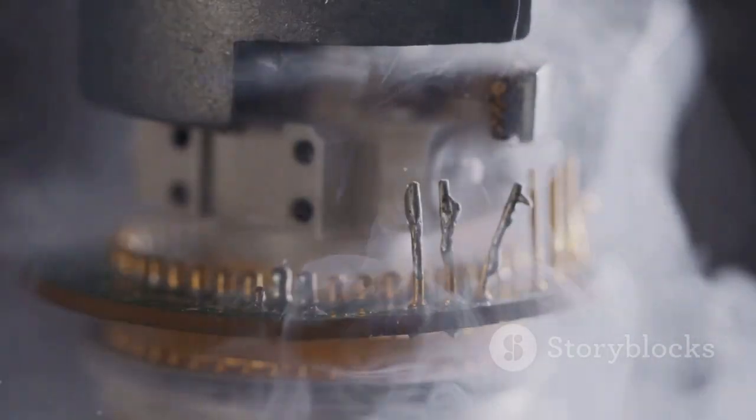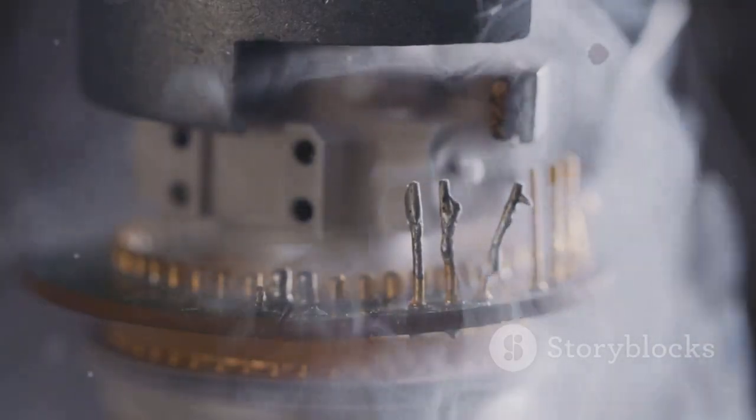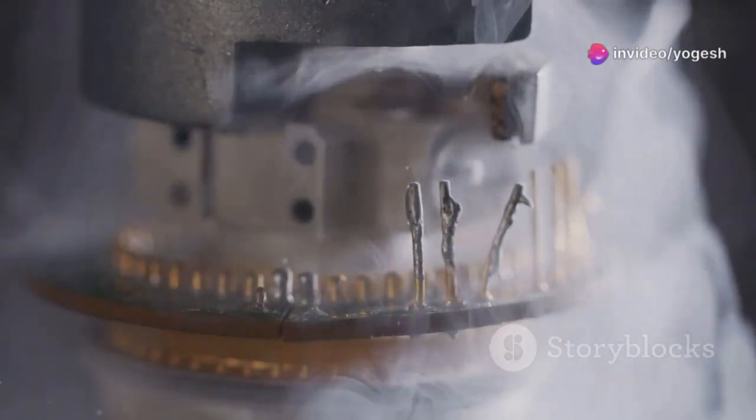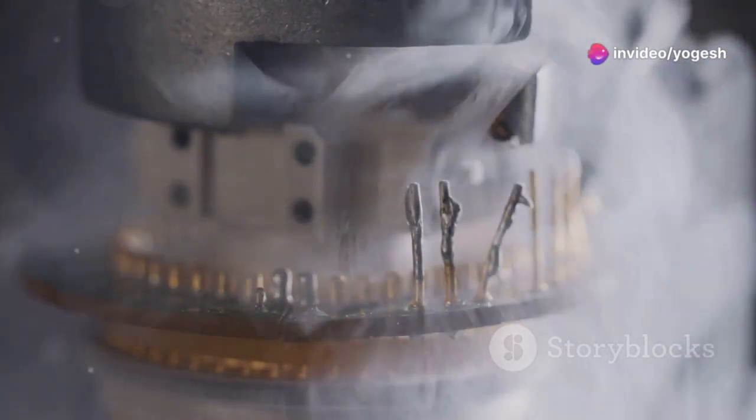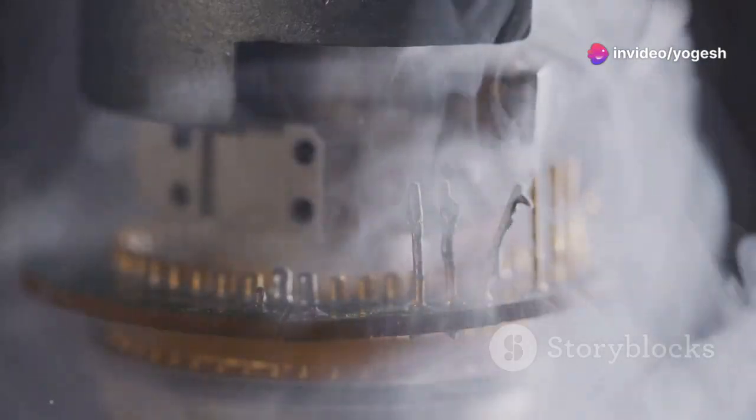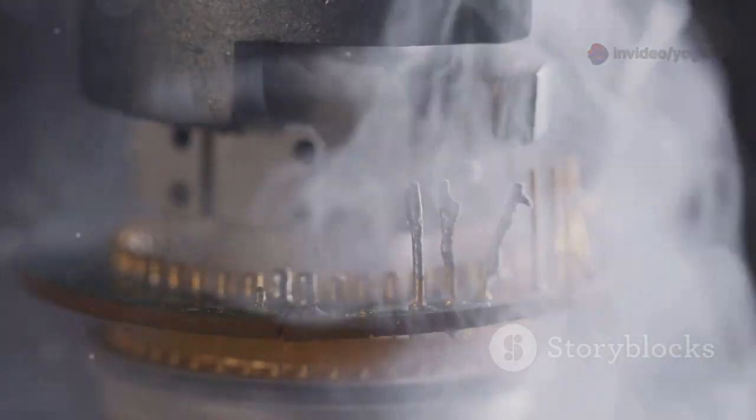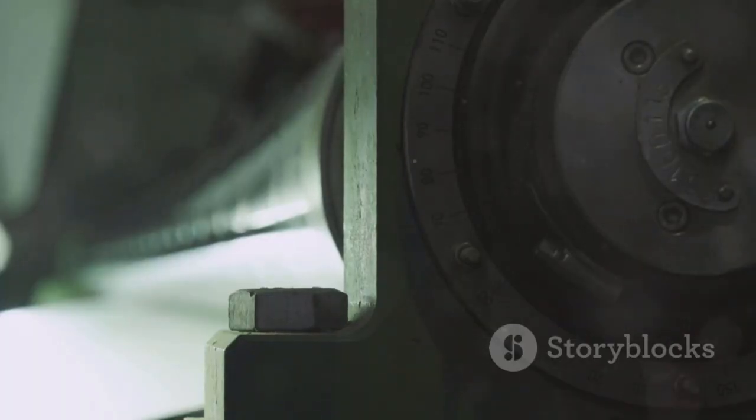The full section is the workhorse of sectional views. It slices straight through the entire part, revealing everything inside as if the object were cut cleanly in half. This method is perfect for symmetrical parts, as it displays the complete internal profile in a single, easy-to-read view, making it simple to spot any internal features or cavities.